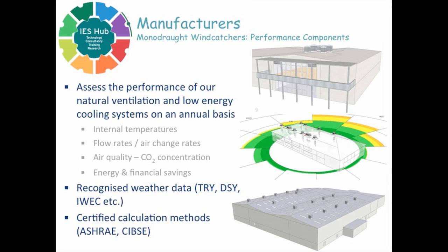There's the diversity in output data which we can analyse in accordance with the use of our systems, but it's also the fact that we're using recognised weather data, whether it's CIBSE accredited weather files, your TSYs, your DSYs or your IWEC files. We're using annual simulations, so we can not just look at a steady state scenario under which our systems perform, but we can actually look at how they interact with the building over the course of the year, not just during summertime operation, but during wintertime operation. And we're using certified calculation methods.